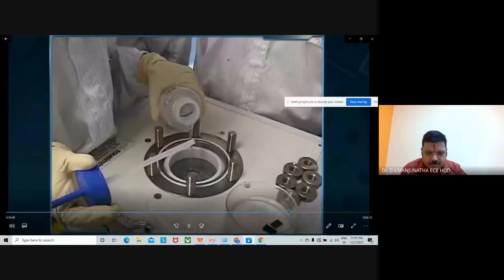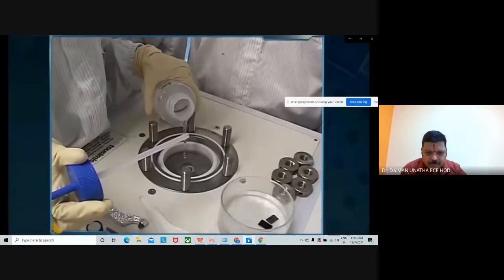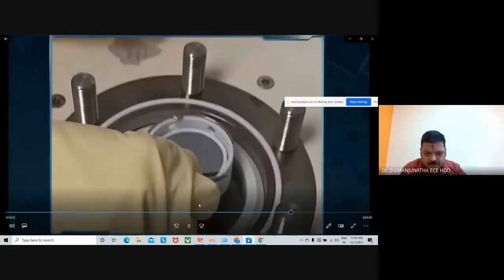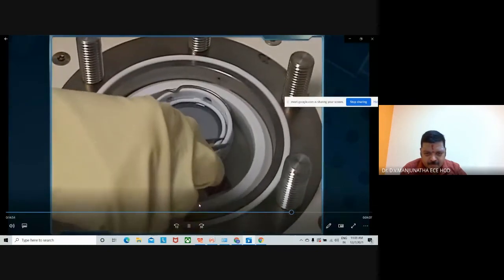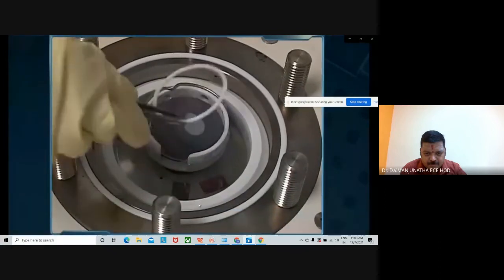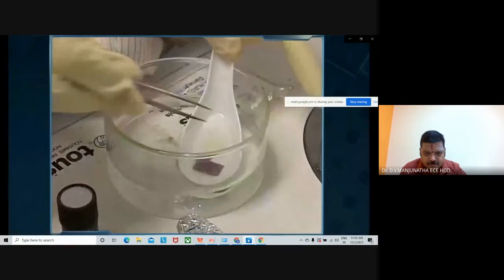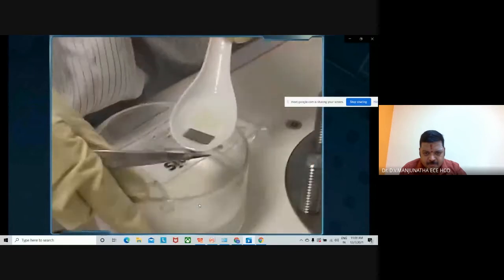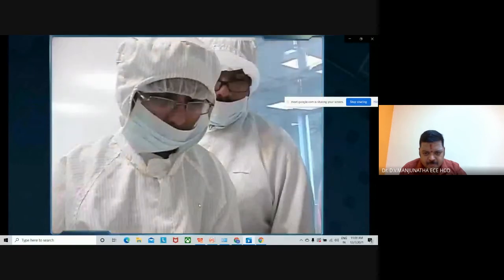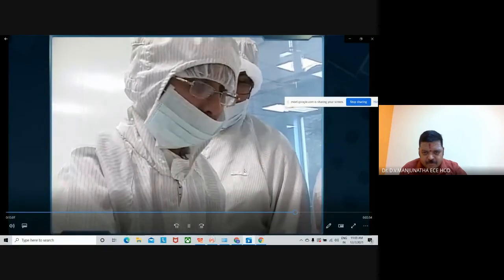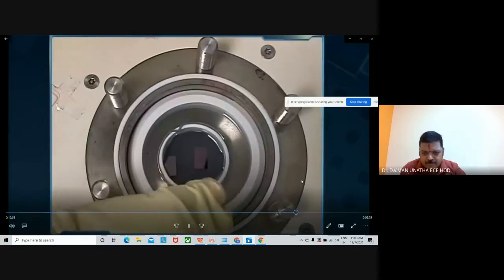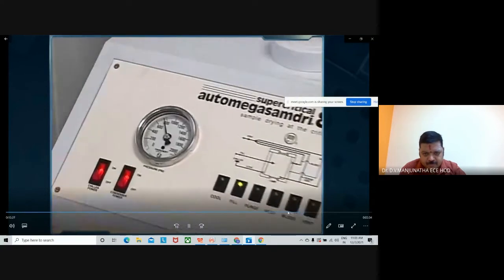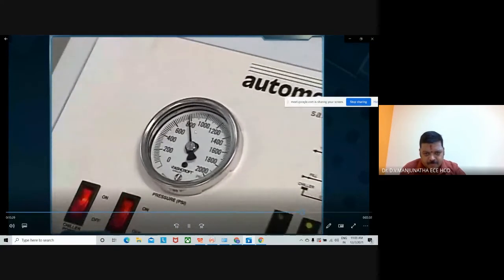Next, we fill the CPD chamber with isopropyl alcohol to immerse the special sample basket. At this stage, exposure of samples to air increases chances of stiction. So we transfer submerged samples along with IPA into the basket with a large spatula. The equipment is turned on.